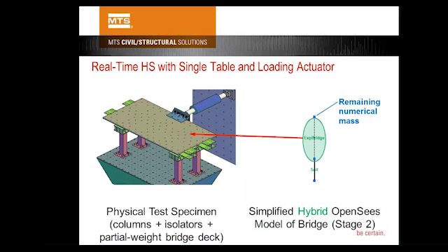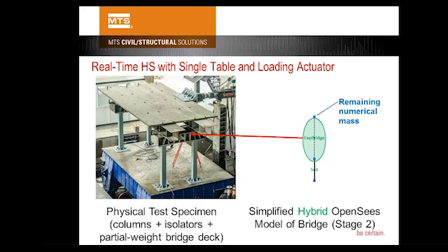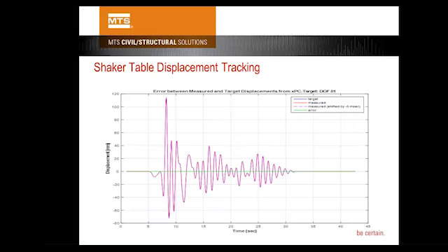So you can see, this is the physical substructure. The weight is gone in the numerical substructure, and the effect of the weight is applied by the loading actuator. So this is a shaker table coupled with loading actuator hybrid simulation. We used the delay compensator and very successfully executed this test.